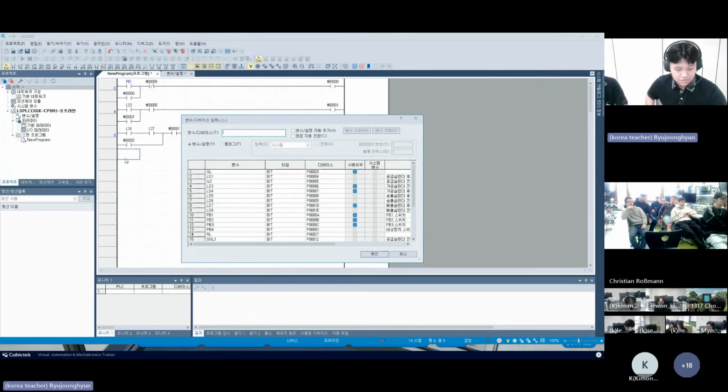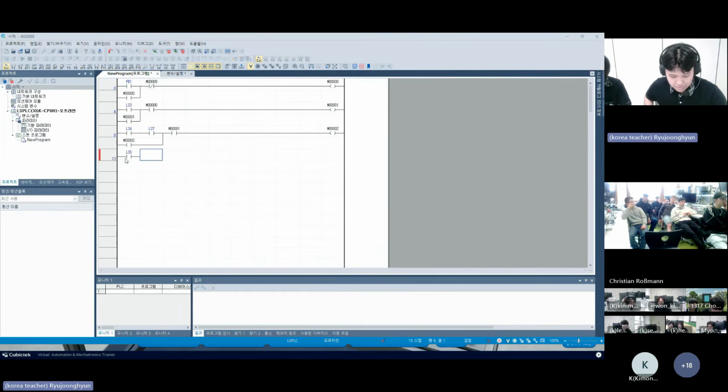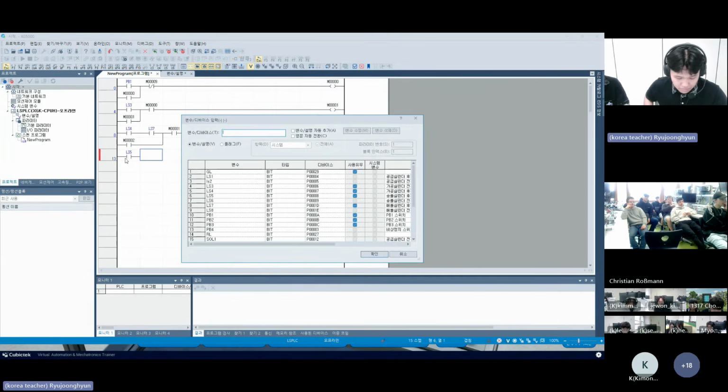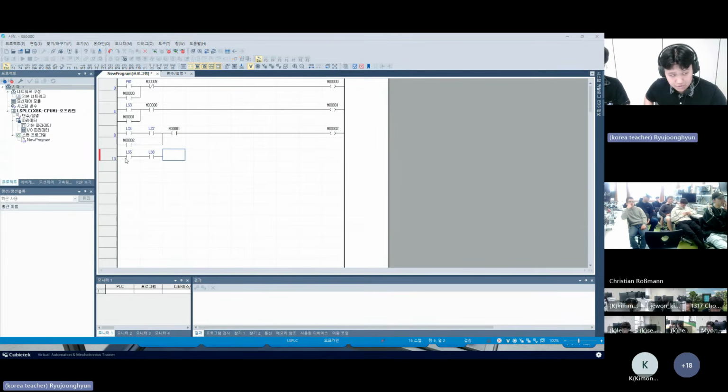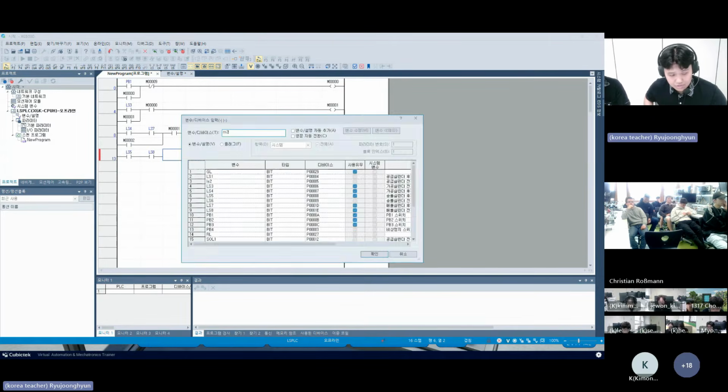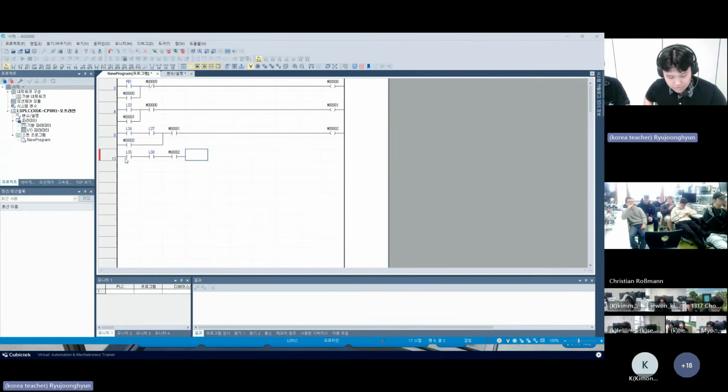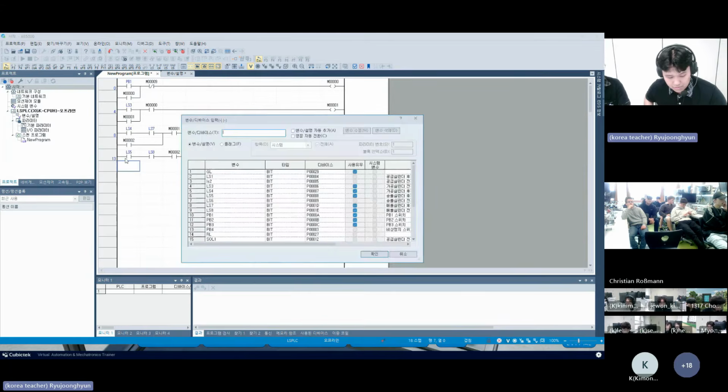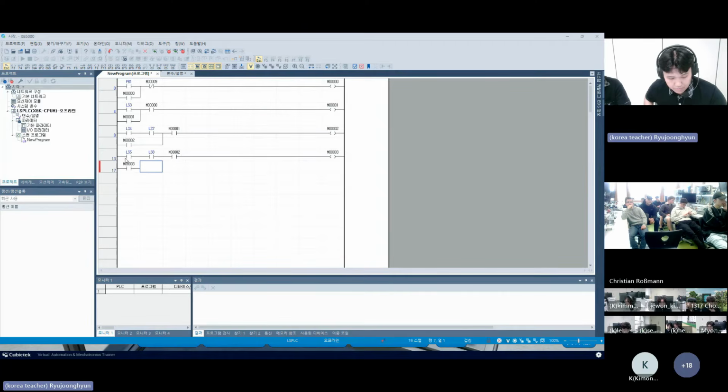On the M3, the transmission cylinder moves backward, so use limit switch 5, and the discharge cylinder moves forward, so use limit switch 8. Use M2 and use M3 for the coil and self-holding circuit to prevent the operation from occurring first.